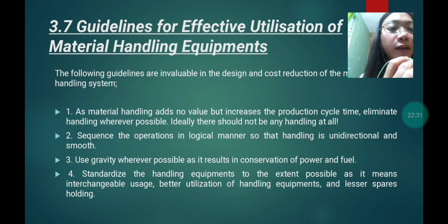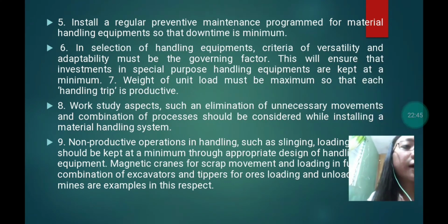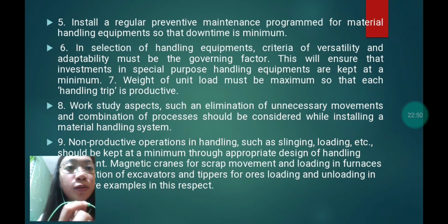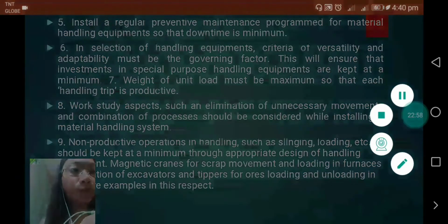Standardize the handling equipments to the extent possible as it means interchangeable usage, better utilization of handling equipments, and lesser spares holding. And next we have, I need to move this. Install a regular preventive maintenance for material handling equipments so that downtime is minimum.